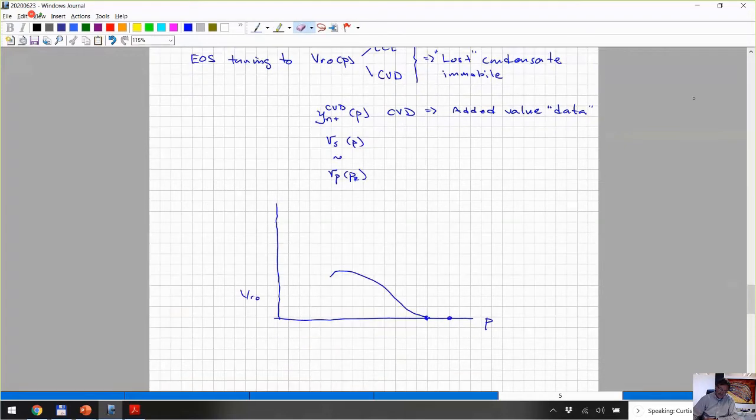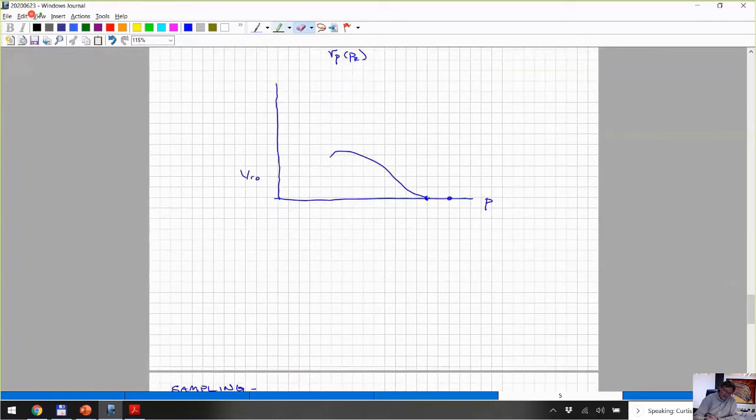Of course, it depends. I'm going to plot the CVD. This is the CVD relative oil volume: oil volume, which changes with pressure, divided by the dew point volume, which is a constant. So this actually reflects the actual oil volume in the cell. And this will often flatten out, something like that.